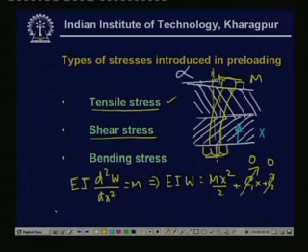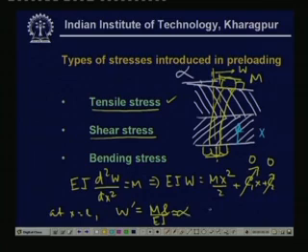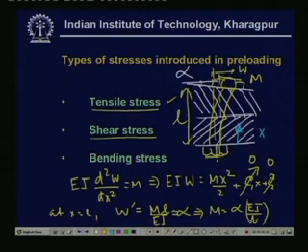Now the slope at x equal to L is w prime, where w is this displacement from this axis. So this becomes ML divided by EI, and that is approximately equal to alpha. So once alpha has some value, then we can get M to be alpha EI divided by L, where L is the length of this bolt.